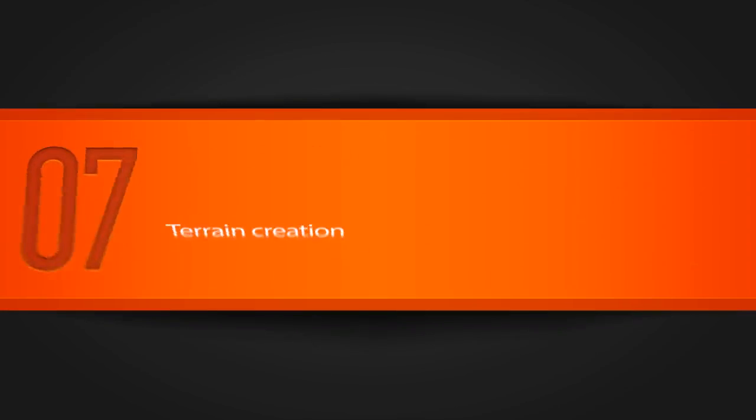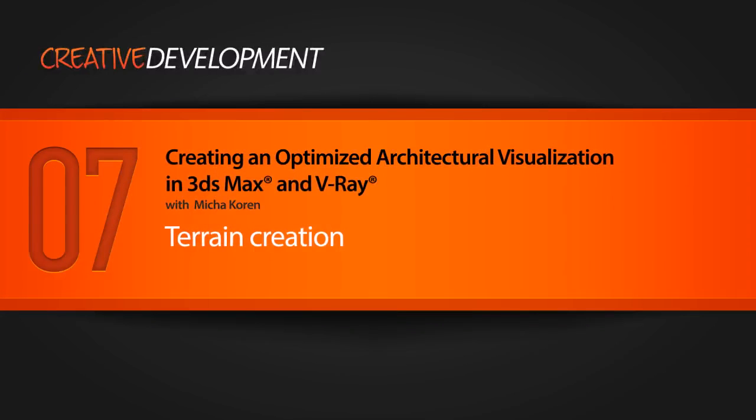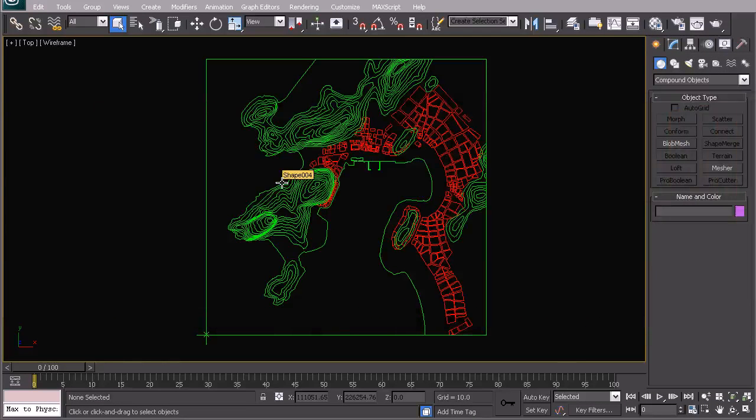We've now finished with the contours, and from the last video where we started moving all the contours up, we've completed that and all the contours are now in place. Now this video is going to cover how we take those contour lines and apply a terrain mesh. We're then going to take a poly mesh object and conform it onto that to make the mesh a little bit neater. And then we're going to cut that mesh out into the terrain and the ocean side, and then basically split it up into our 16 squares so that we are ready for modeling and texturing after that.